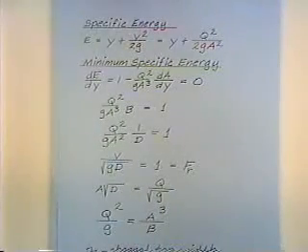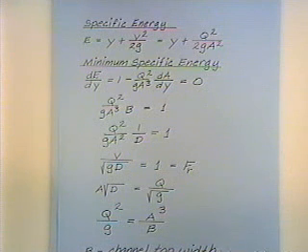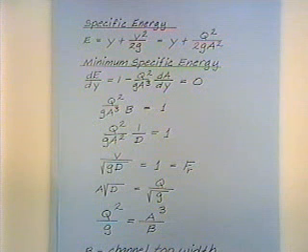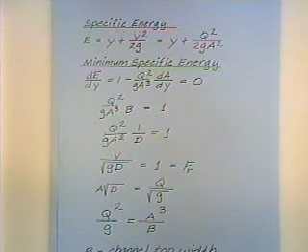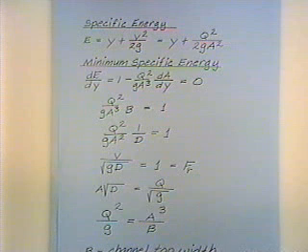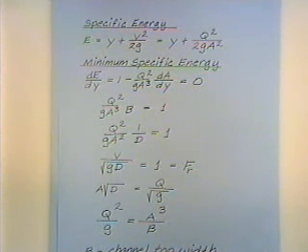On this page of notes, we've written the specific energy. Again, it's the depth plus the velocity head. You can write the velocity head as v squared over 2g, or recognizing that the velocity is the discharge divided by the area, you can write it as Q squared over 2gA squared, just plugging Q over A in for the velocity.